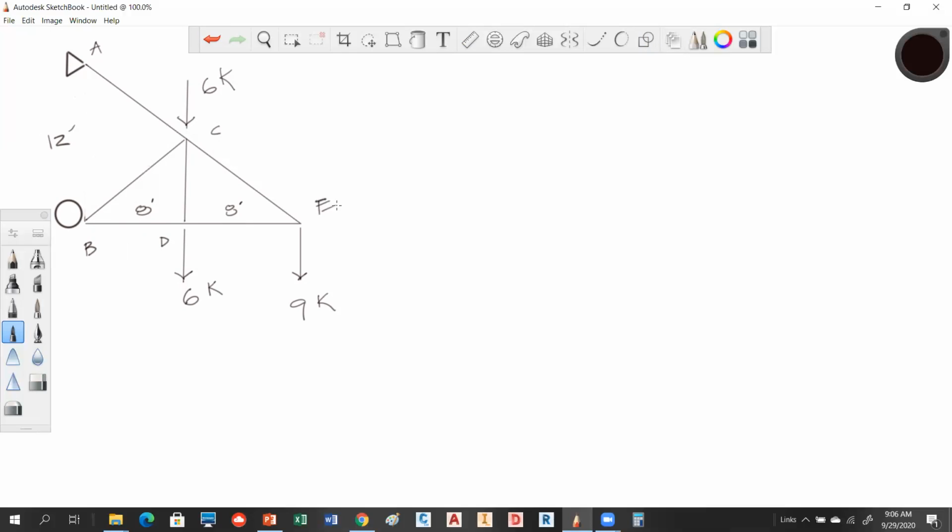Okay, does everybody understand our truss? Okay, so let's say we need to solve members AC, BC, and BD. So that would be over here, right? AC, BC, and BD. So what I'm essentially saying is I could take a section cut right there. Does everybody agree with that?